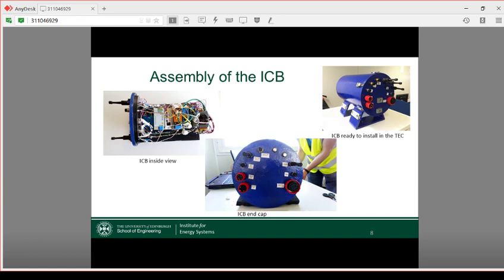And this is an interesting story because it's very easy to go and buy a very expensive pressure vessel that's rated to a couple of thousand bar, sort of 6,000 metres and all this kind of stuff. We want something that goes into 50 metres of water. So we can't afford that expense. And the other problem is that in 50 metres of water, you feel the effect of waves on all the seals. So we found things failing much more quickly than they're supposed to fail.